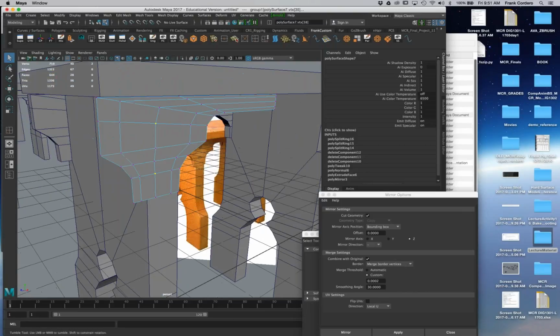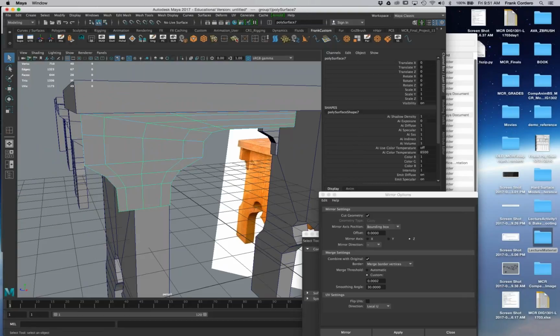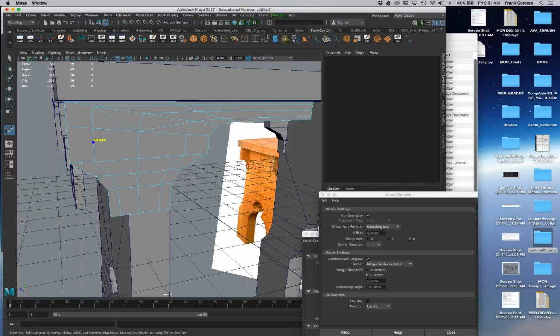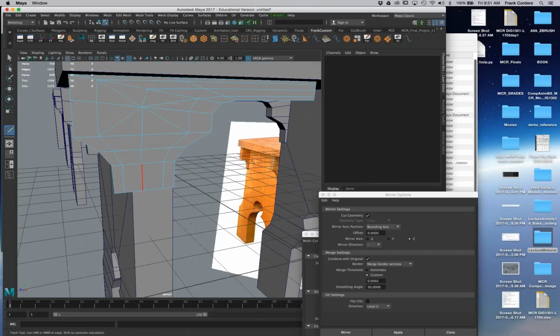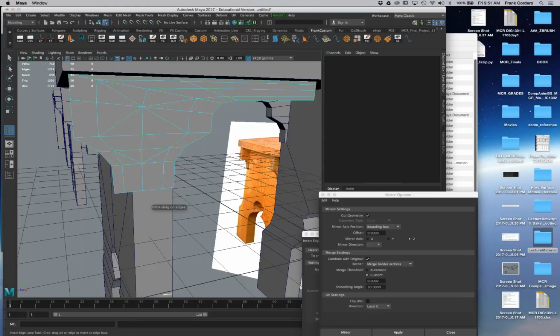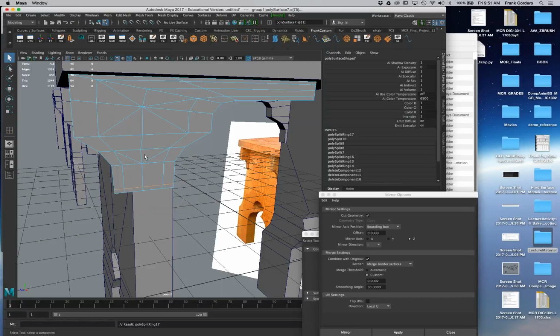What I'm doing right now is creating an X marks the spot. With my multi-cut tool, I want to create an X marks the spot over 4 faces. See what I'm doing here, guys? Boom. I want to set up my hole cuts with this X marks the spot. I also think I'm going to isolate the hole cut down below and keep it inside the shape. In other words, I don't want it going to the edges. I don't want these points. I want to keep this free for a reason.